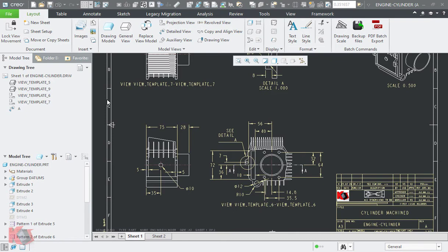Today I am going to show how to exploit the grid functionality in the Creo software, and implement this projection approach. To start, first rename the views with respect to the base view. In this example I am going to rename the base view to be V0. Then the next views' names are as follows: V1, V2, V3 and so on.